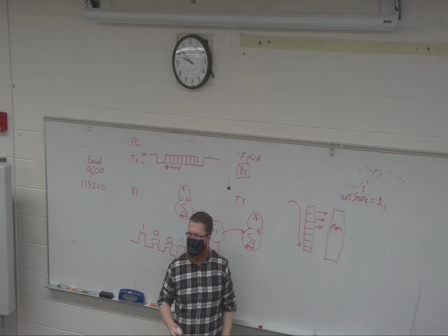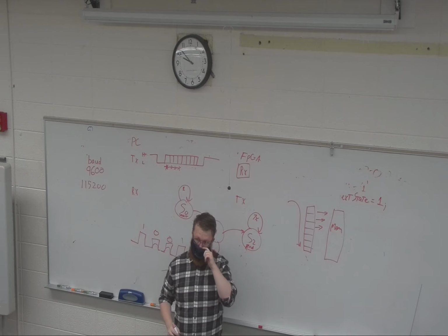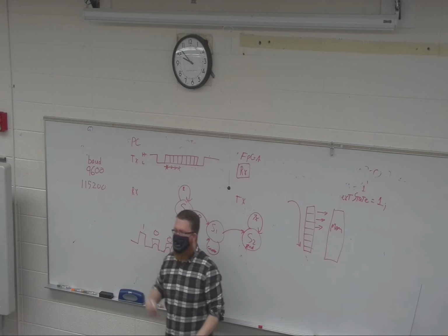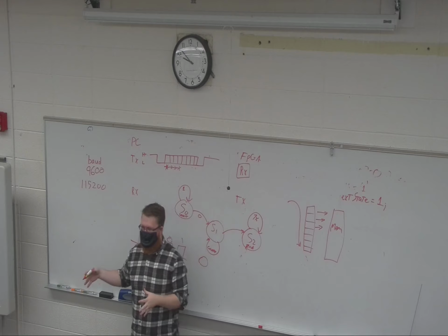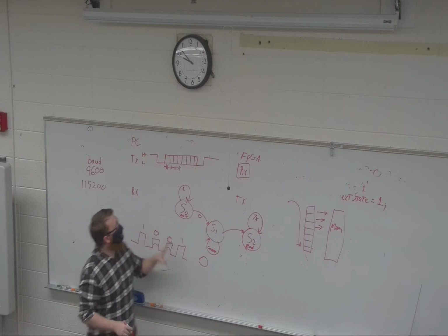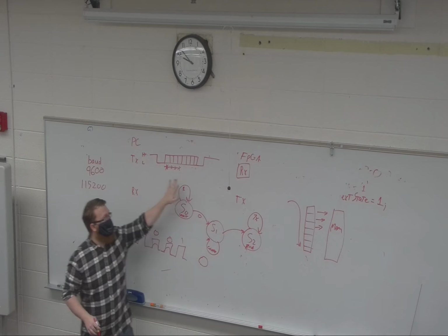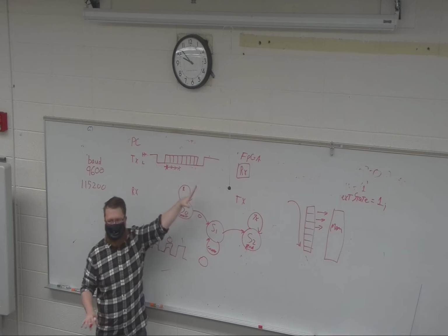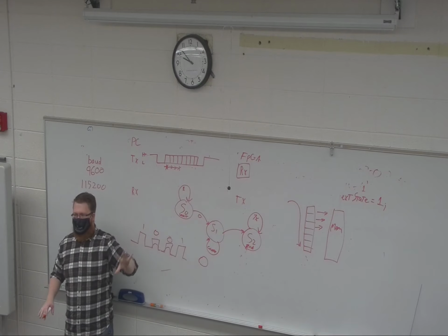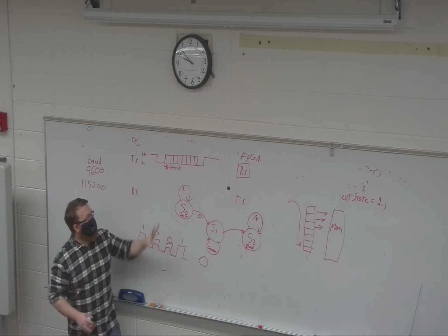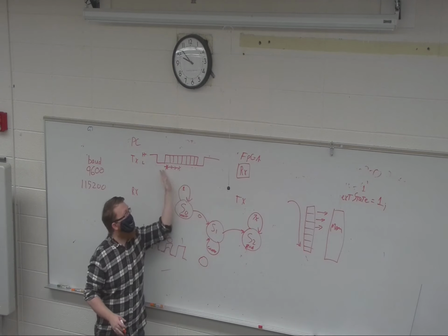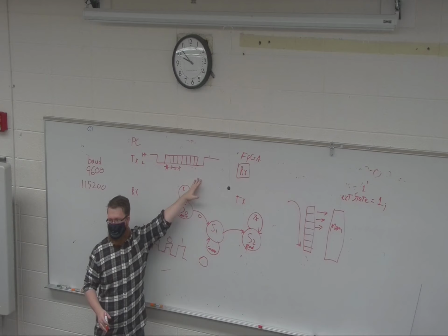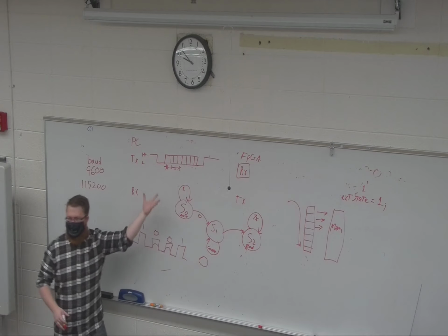Yeah? And we're just doing 8 bits. Just 8 bits. So is that how it knows when it's done? Exactly, yeah. You have to define how many bits it sends at a time. We call another term for that the start bit, stop bit, and optional parity bit. We're not going to do parity, but start bit, stop bit, and optional parity are all what we call overhead, right? Because I have to send 3, well in this case 2 bits extra for every 8 bits that I send.